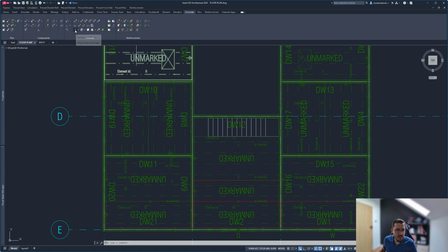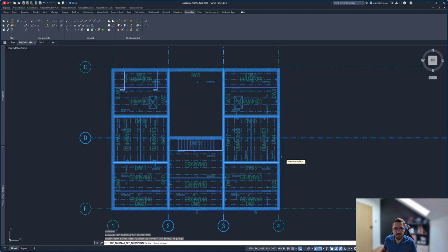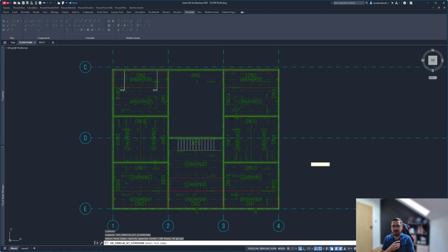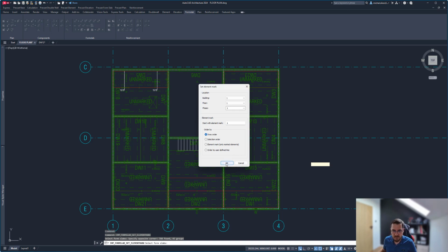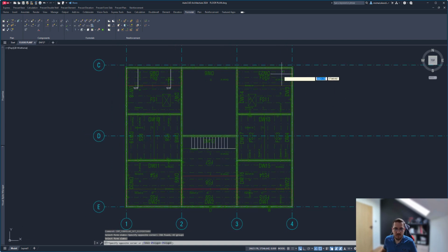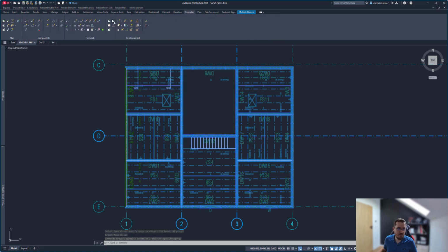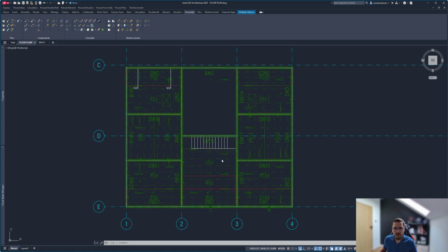With that, let me go ahead and actually, in this instance, let's set element marks as well, because you need to set those element marks for form slabs. So I'll just select that. It will find which form slabs are identical, which are not, and yeah, that's it for draw order. So those elements, those slabs are now done, and now I can save those slabs. The difference between form slabs and double walls is I don't have to actually create the drawings to save them to database. I can just save them, and once they're saved, they will be visible in the project manager. So we'll have a preview of that as well, and they're done.